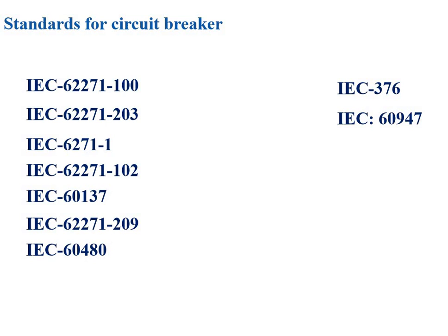The next is IEC 60947, which gives the degree of protection provided for enclosures for low voltage switchgear and control gear. Then IS 325 is the specification for 3-phase induction motors. Then IS 2516 is the specification for high voltage alternating current circuit breakers.